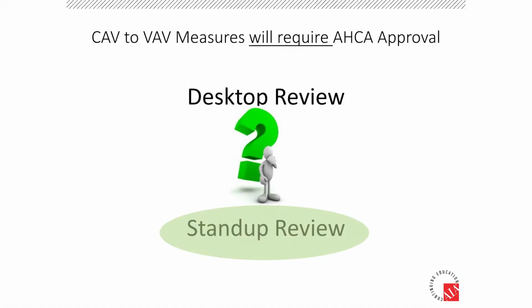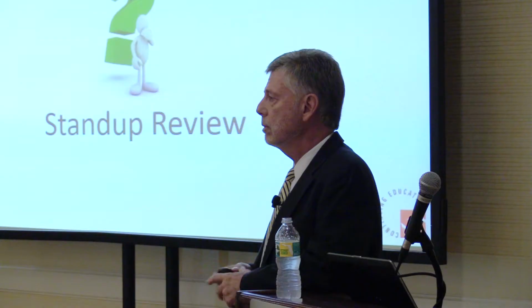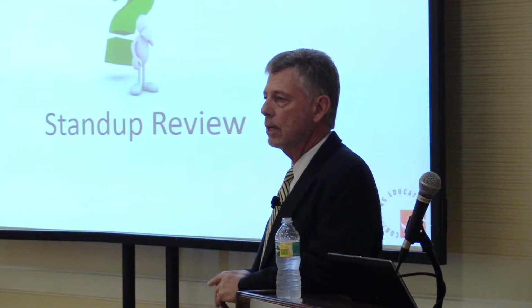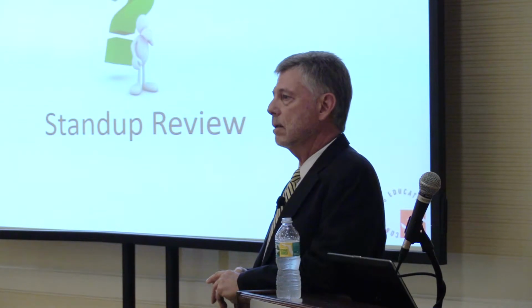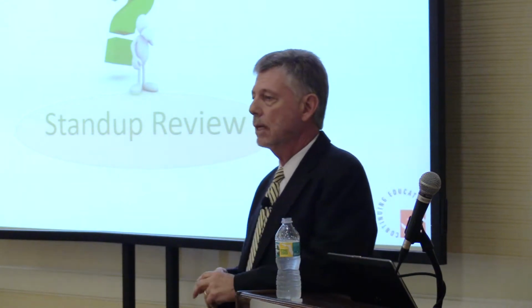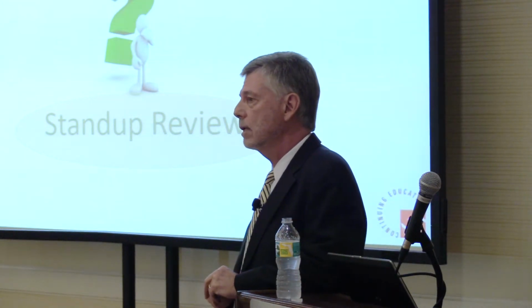So what does it require with AHCA? When we did our first project like this, we were hopeful that the only thing required would be a desktop review, which is essentially a letter, a short explanation as to what we wanted to do, and they would stamp it approved and we'd be on our way. We were hopeful for that, but deep down we knew that probably wasn't going to be the case. And AHCA does in fact require a stand-up review to convert, in the sense that I'll be discussing today, constant volume boxes to variable volume control.